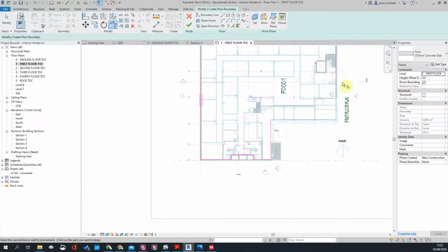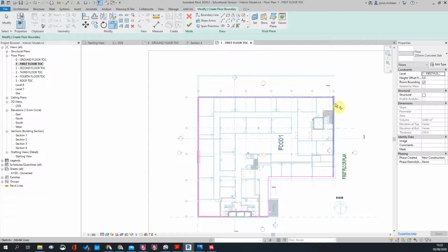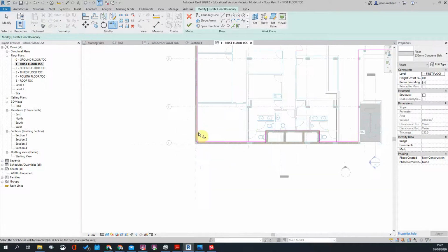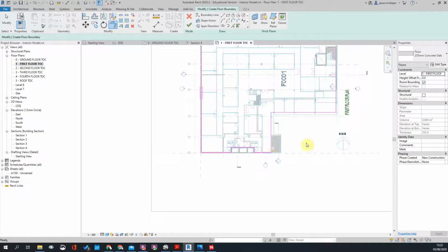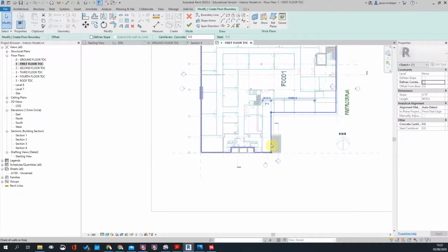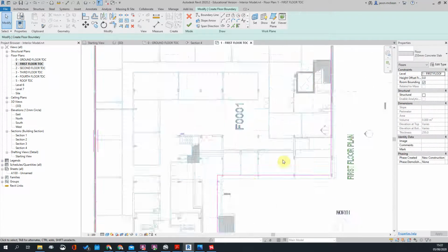because there's going to be a balcony here, which I haven't really done, but I'm using the floor slabs to kind of work out the edge of the balcony. I can always offset this floor later. So remember, they need to be closed loops. It works just like a fold region, for example. So everything needs to be a series of closed lines. There should be no open ones.